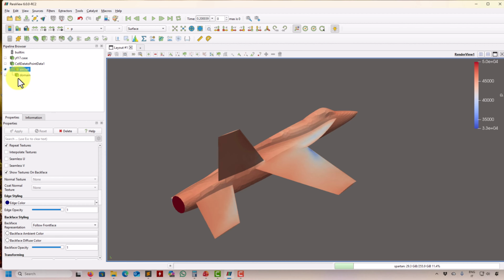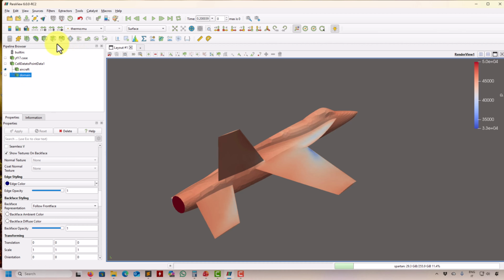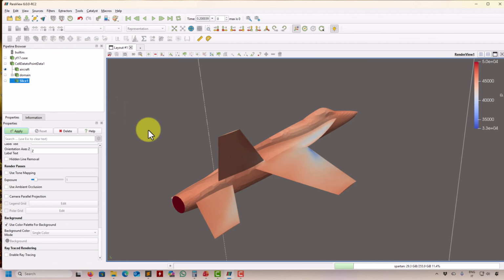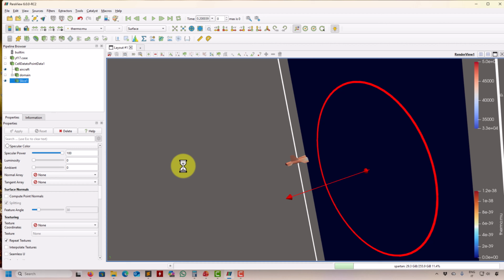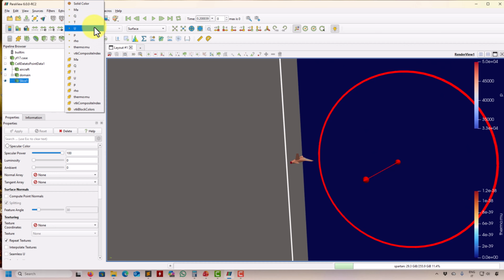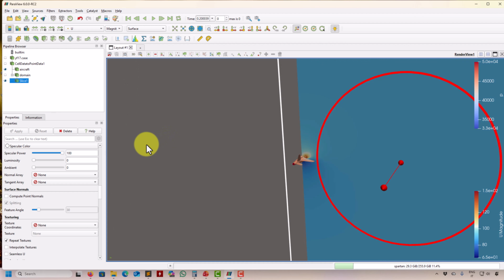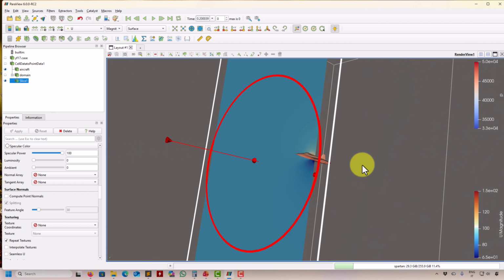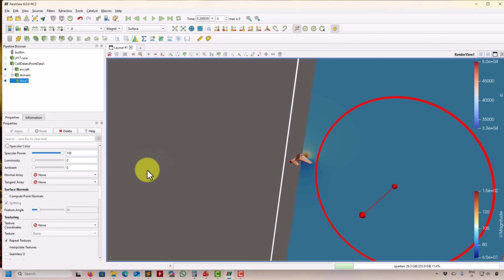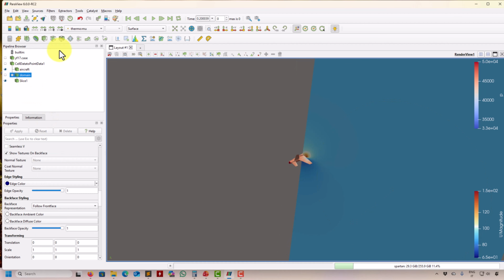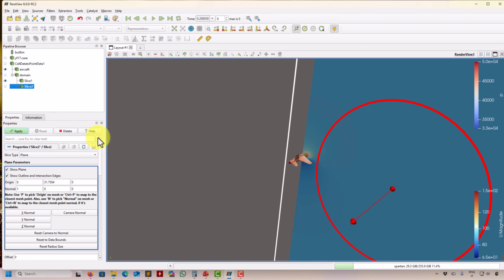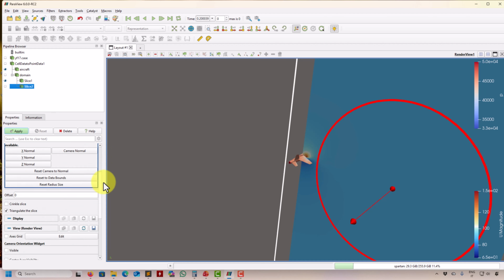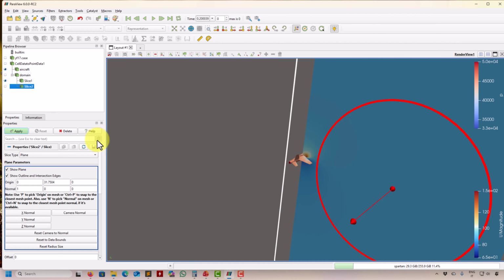But that is not what I want to do. I want to slice my domain. So if I go here, there you go. Now apply, and there you go. Then I can plot velocity, and you have your velocity there. You can create more slices. Let me create another one, and then you can change here. Remember, I have the advanced features on, so you don't see all the options because of that, but here you don't need it. You can choose your reference planes, the location, and so on.